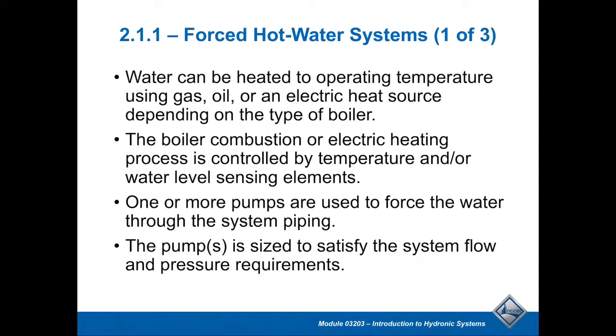So generally, what we're going to have to do in this boiler system is control its temperature, whether with some sort of sensing device, such as an Aquastat, and we'll look more at that. We'll use either one or multiple pumps to push that water through the system, or circulate the water through the system, is normally what happens.